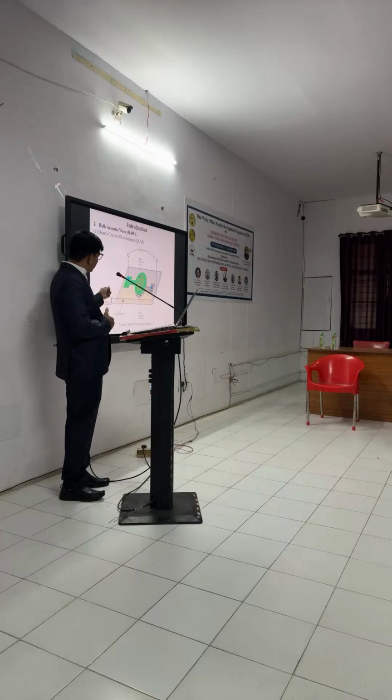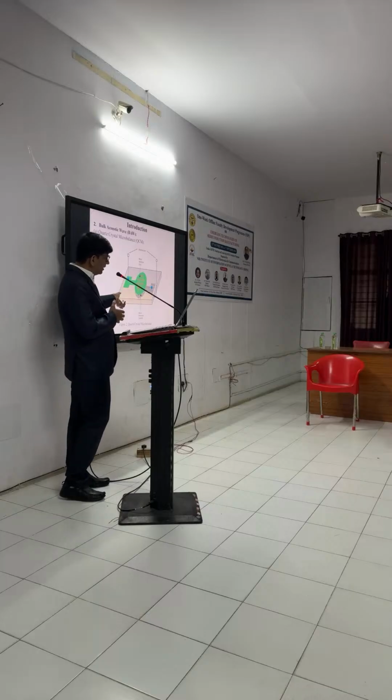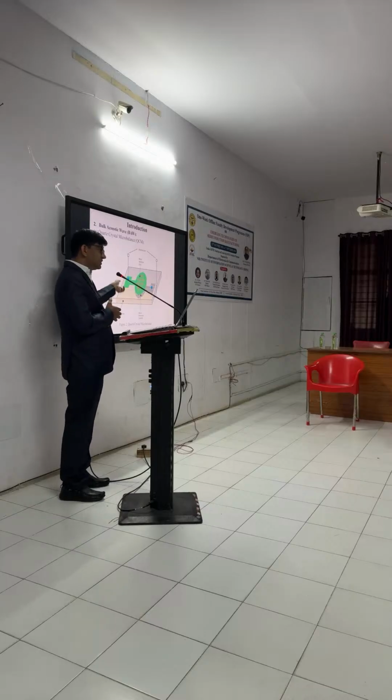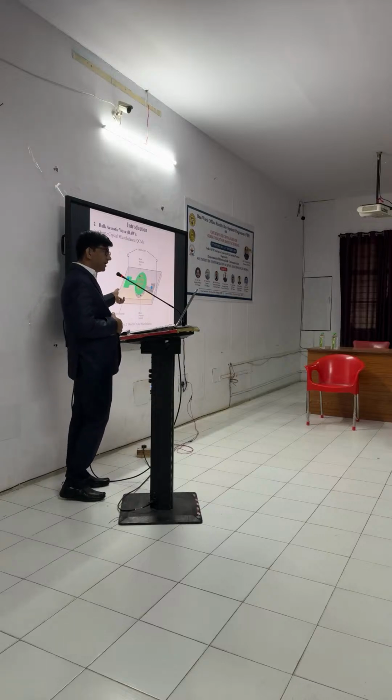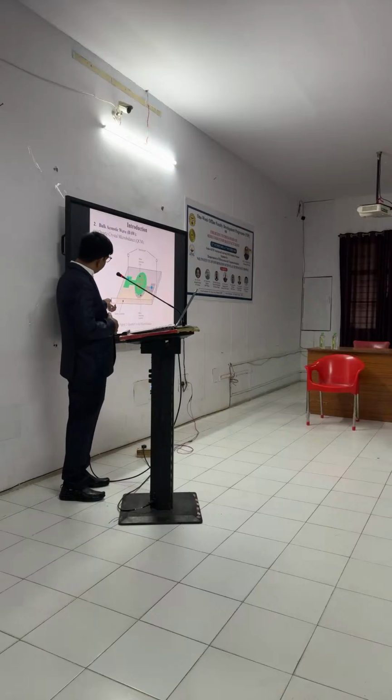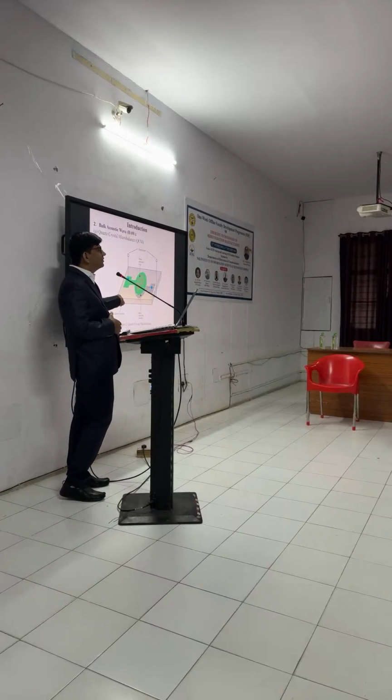Okay. So once we apply a signal between the bottom and top electrode, stress will be generated, and due to this stress there is a mechanical vibration and our resonant mode will be generated. And this resonant frequency will depend on the thickness of the piezoelectric substrate.